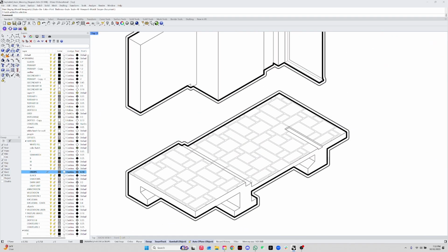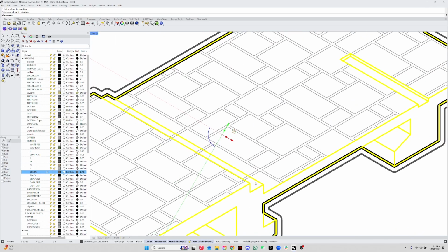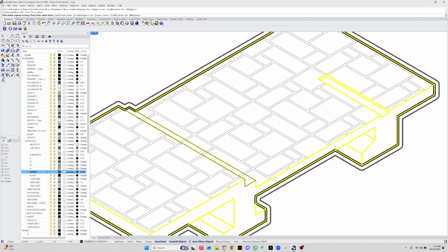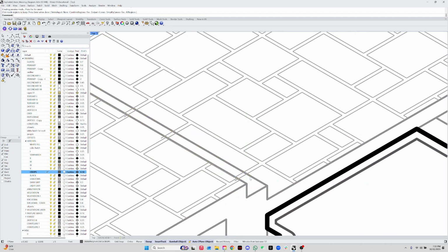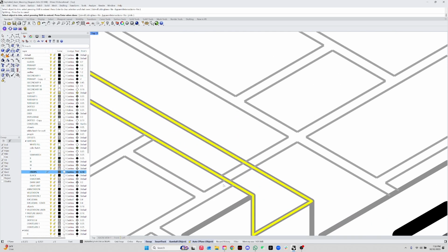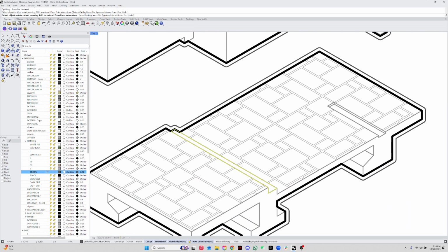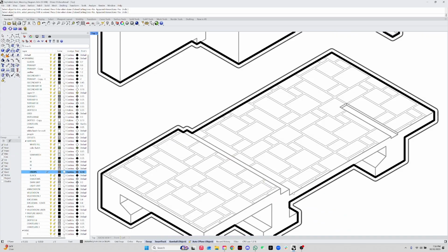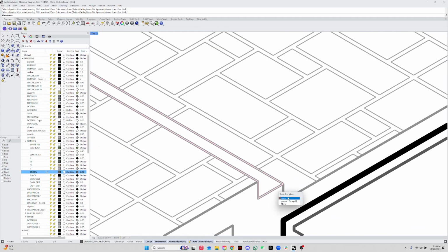That's completely okay. What I want to do is get this line inside of this. Like I want to get this boundary. So for that, I'm going to do curve boolean. I'm going to just go like this, get that outer line as a reference line. And then I'm going to click it and I'm going to do trim. All right. So when I trim, it's going to delete what's underneath. So you can do that technique if you have excess hatch that is going over.